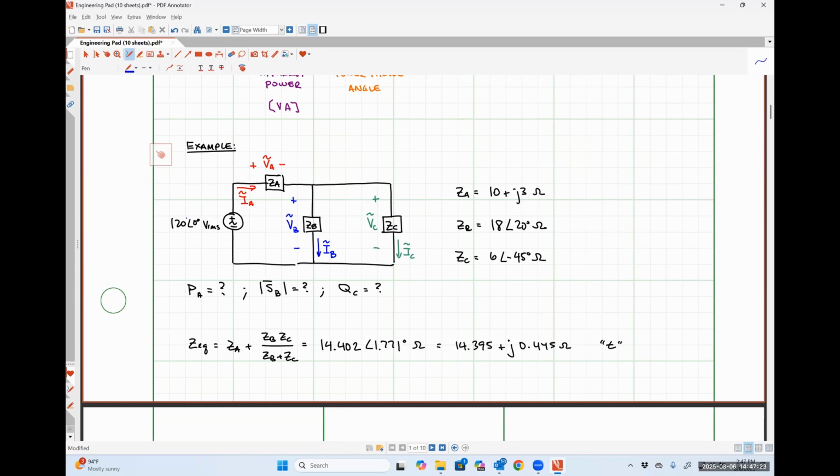So because we got a negative number for our reactive power, that means that this element is supplying reactive power. So it's obeying the exact same rules that we talked about when we had just simple DC circuits. If we calculate absorbed power and we get a negative result, it just means supplied. Okay. What we'll see here in a little bit is that realistically, that just means that there's some capacitance as part of that impedance, which should make sense because we have a negative phase angle.